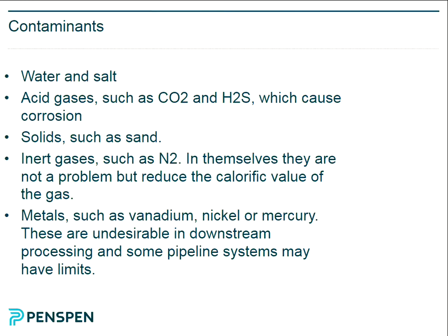In Mexico they use nitrogen as a production enhancement. In the Cantarell field, they've got a massive nitrogen plant onshore. They create nitrogen using a cryogenic process, taking it from air, and then pump it offshore and put it downhole to enhance production. But you're right, they ship CO2 around the US and use it for enhanced production. In fact, there's a company called Kinder Morgan that has a business in transporting CO2 for that purpose.